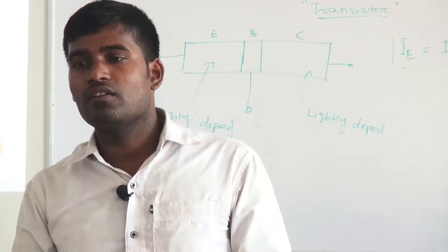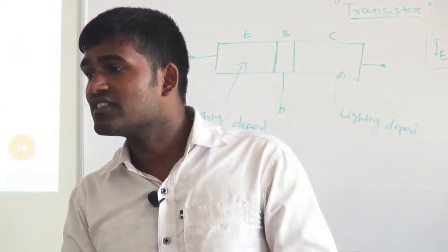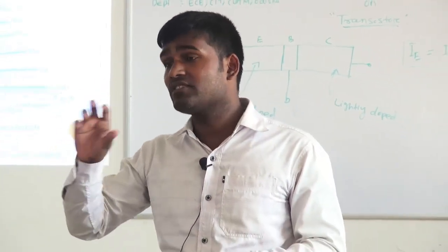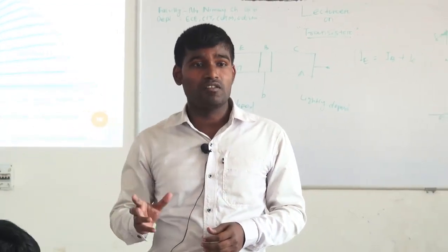That point is known as Q point, quiescent point or silent point. So one thing is that you have to maintain the Q point at the middle position of the load line, because it will give reliable output.